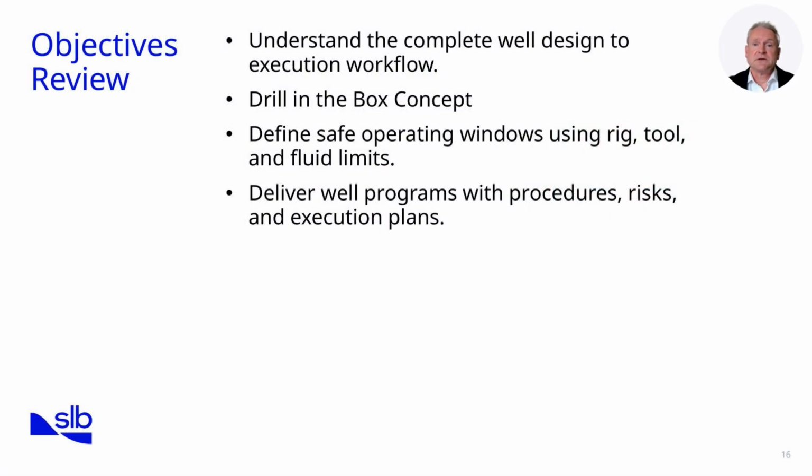Let's take a moment to review the objectives we set at the start of this submodule. Our first goal was to understand the complete well design to execution workflow. We achieved this by stepping through the design process, from geological inputs to casing, fluids, drilling mechanics, and final procedures. The second objective was to explore the drill-in-the-box concept. We saw how defining operational boundaries provides a clear framework for safe, efficient drilling, and how staying within those envelopes reduces risk.